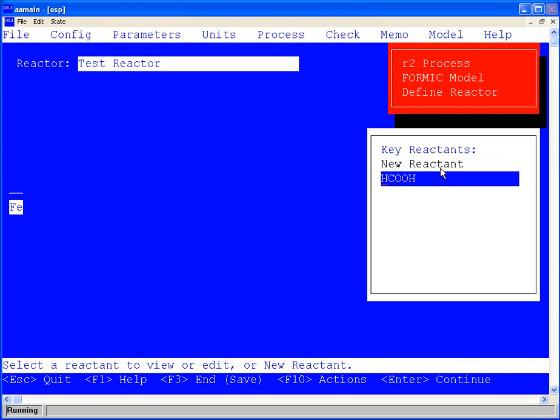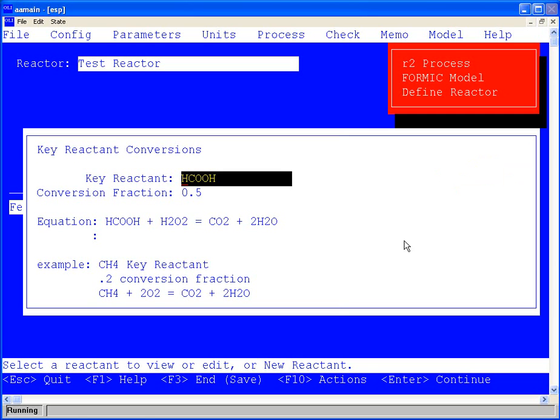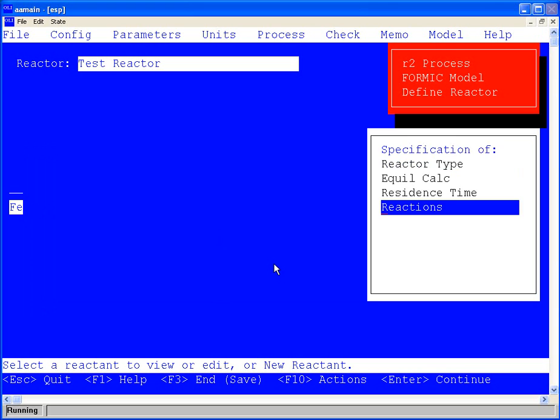We can go back and edit it to take a look at it in detail. But all of these species, the formic acid, the peroxide, the carbon dioxide, and water, they are the species in the inflow list. You notice that there are no ions here, vapors or solids, or any other designation. It can only be in terms of inflow species. Okay, we're now ready to run it.